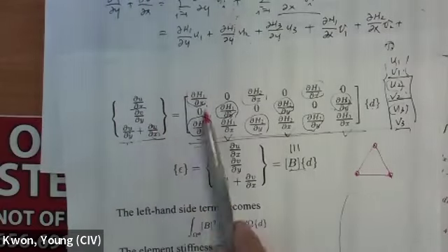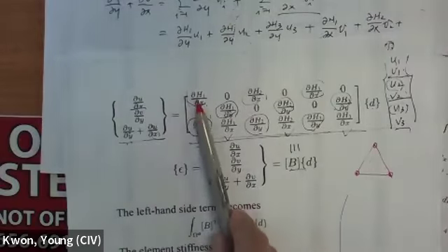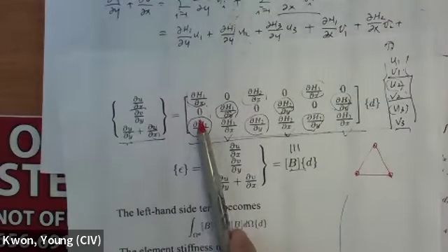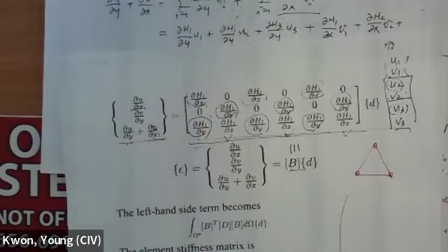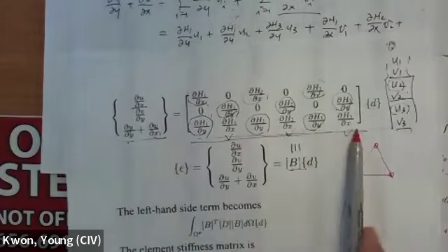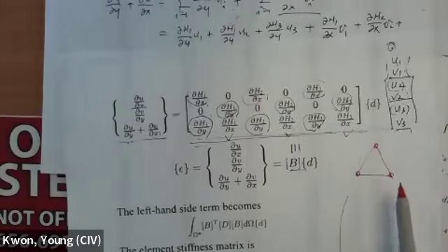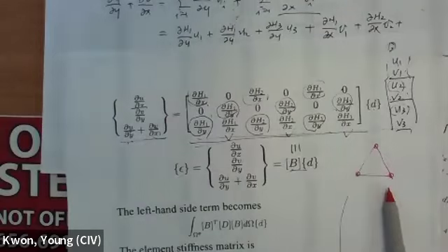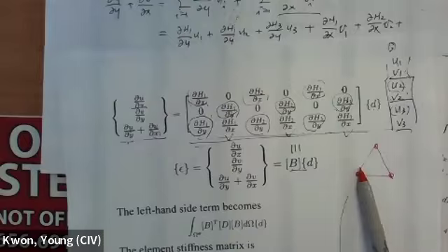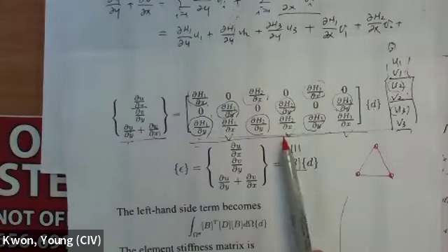So that's 6. So the number of rows is going to be either 1, 3, or 6, depending on a 1D, 2D, or 3D problem. And the number of columns depends on your degrees of freedom, from the selection of elements. So if you use that one, how many degrees of freedom? 6. So that is going to be 3 by 6. Do you get it?